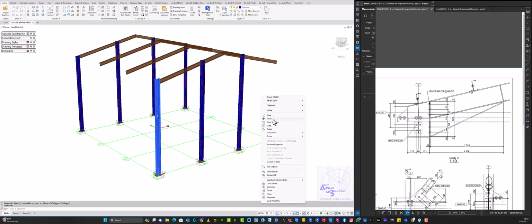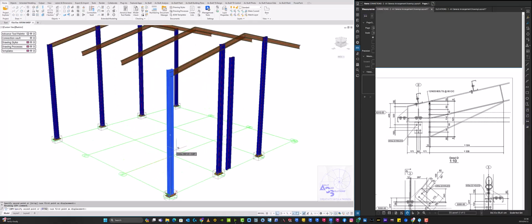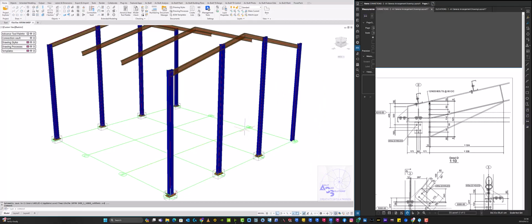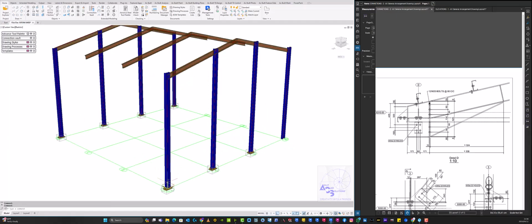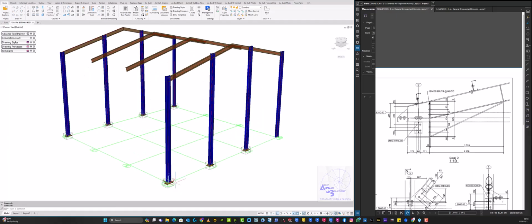Let's say you were copying a beam or a column in any of the projects. For example, when you copy this column to that node there, it's going to go with the connection for the base plate to the new position. All right, let's see what happens. So we copy the column, and mind you, here we just selected the column only. We did not select any elements of the base plate. So there, hit enter. So you see, it did not copy with the connection as well.